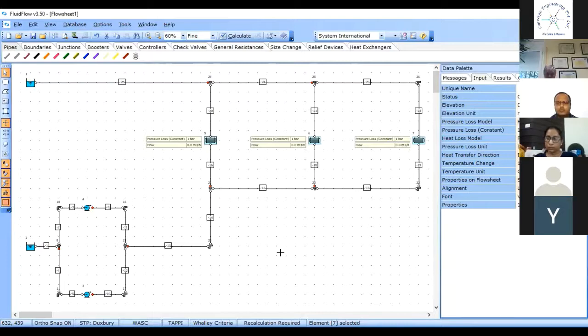Okay, so let's assume that we had done the Aspen EDR simulation for these 3 exchanges, and we found out that each of these exchanges need 100 meter cube per hour of cooling water, right? Now our pump, we have got 2 pumps there, but one running, one standby. So what will be the capacity of each of the pumps? It will be 300, because there are 3 exchanges.